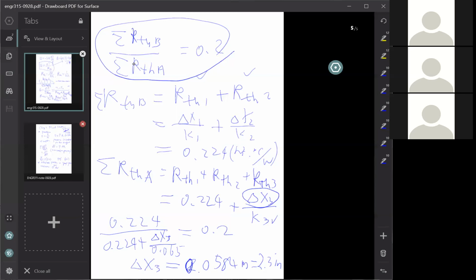When you calculate T1 and T2, you probably need to find T1 first based on the convection part in fluid A. Then you can use the conduction between T1 and T2 to find T2, or you can calculate T2 based on the convection in fluid B. Okay, yes. I didn't even think to use the conduction formula. Now do you understand?